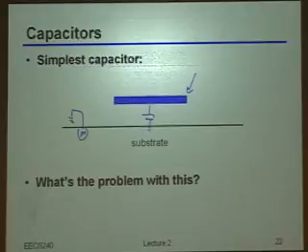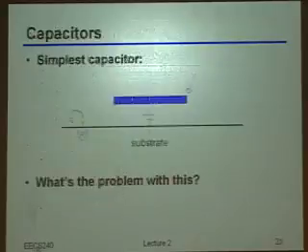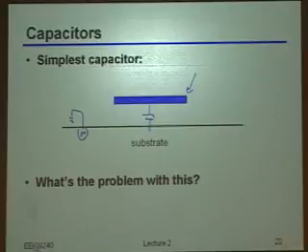So how does this limit you from a circuit standpoint? As an example, what's something you cannot do with this kind of capacitor? Yeah, exactly. You can't do exactly this AC coupling picture that we drew before, right? Because one side of the capacitor has to be ground, right? So in some cases, maybe that's okay. There's actually some specific applications where that's totally fine. But in general, if we want to build a capacitor, we'd like to be able to bias either one of those terminals to something that's not necessarily just ground.